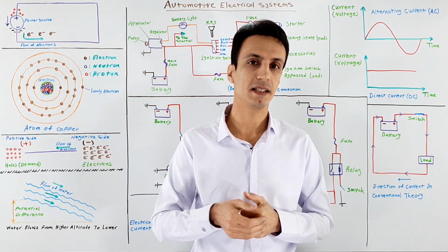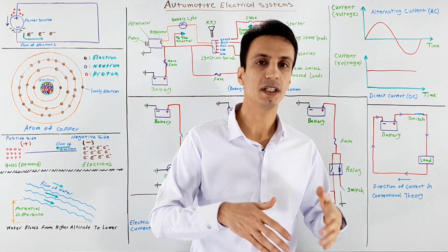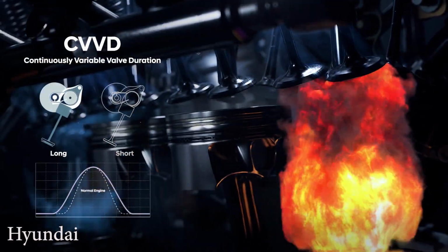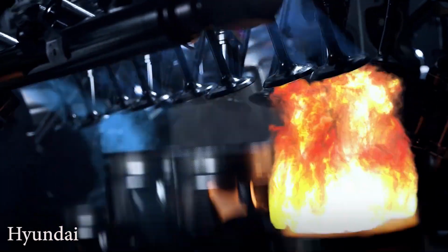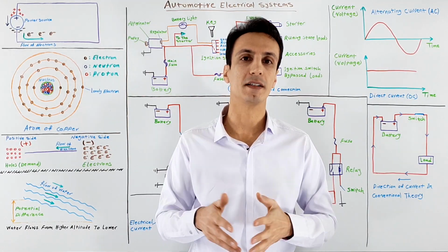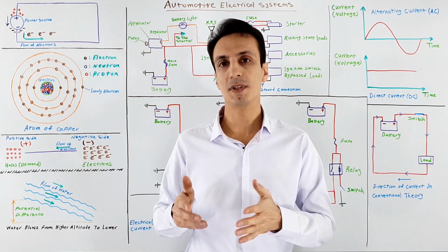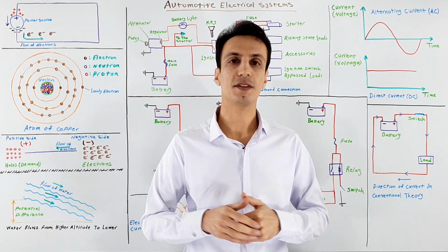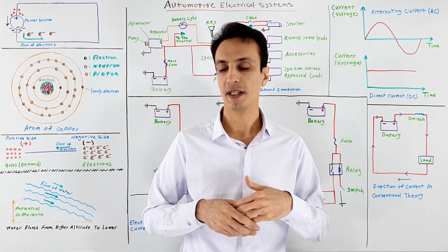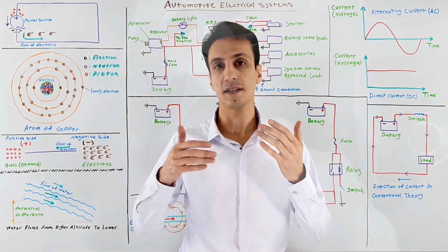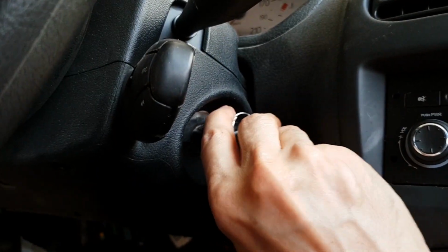Now, you can release the ignition key and it returns to the run position and the starter disengages from the flywheel or flex plate. But the engine continues to run as long as the ECM receives crankshaft rotation signals and enough air, fuel, and sparks are provided. Now we can say that in run position, almost all the electrical systems and components of the car are active and are ready to be used. In this state, if you turn the ignition key back to ACC position, ignition feed for the engine control module terminates and all the relays and drivers of the engine will shut down and the car turns off.